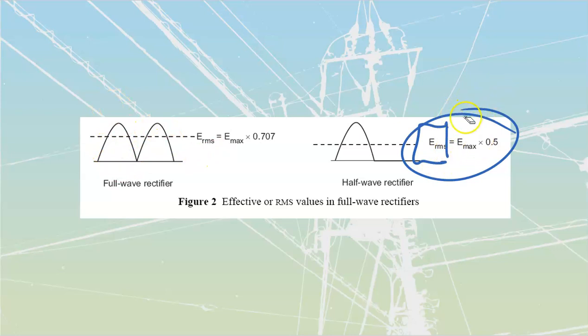The reason that we need to use RMS values is because of this shape over here. We have to use that in order to calculate the actual area underneath the curve, and that actual area underneath the curve is going to allow us to calculate the amount of power. Now, we don't do that at a granular mathematical level. We just do that by plugging in the actual values that we are given. But that is why we still need to use RMS inside of this DC type of waveform, so we can get the true actual power.